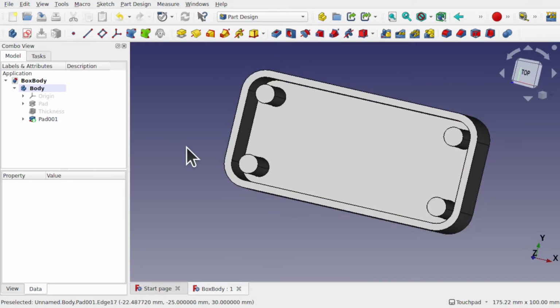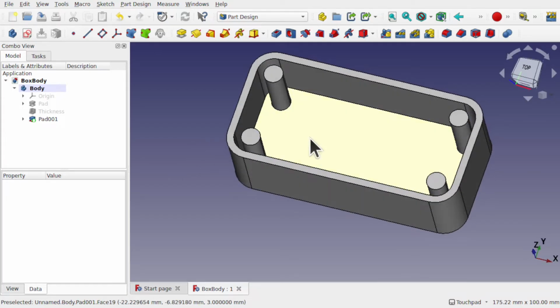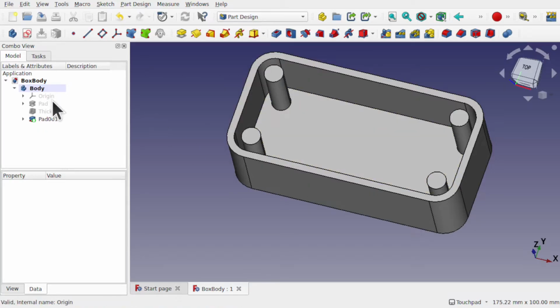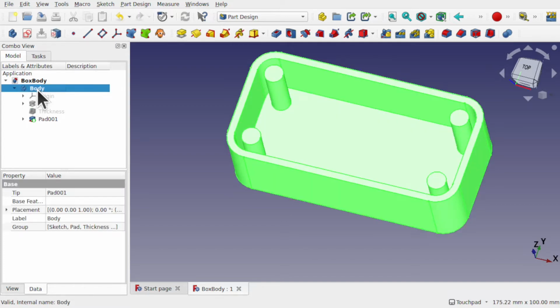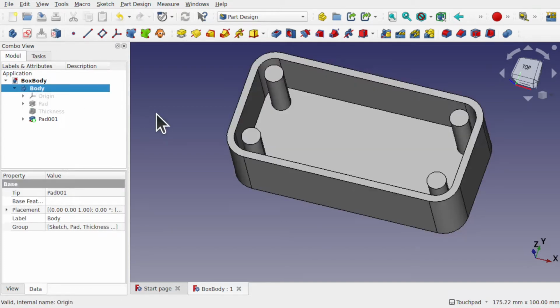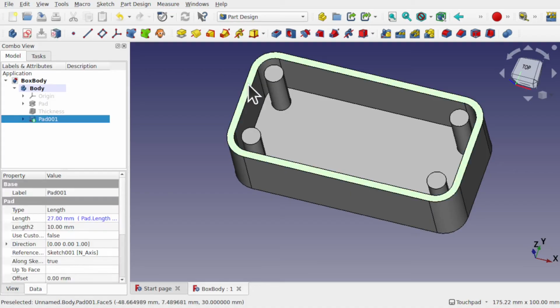So this is the first part of the box. So if I wanted to create a lid in here, what I would do is actually use part of this geometry in Shape Binder. I'll be using the Subshape Binder, but I'm going to be doing something a little bit different with this one. What you can do is keep it on the same file and create a binder in here by selecting this face and the faces of these stems or stalks, and create a binder, and that will be placed in the active body. So at the moment we don't have an active body.